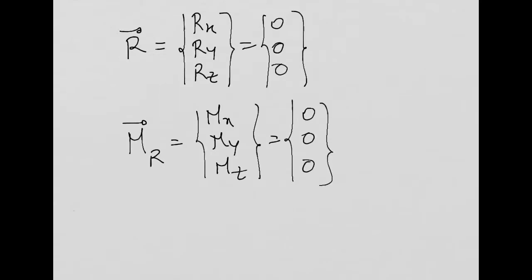Why should the moment be 0? It's the equilibrium equation for the moment. So when we studied the particles, we said summation of forces needs to be equal to 0, the balance of the forces, right? I also gave you an example. You see, we have to do the same for the moments. The moments also need to be balanced. All the moments you have at that point need to be in equilibrium, balance. So that means equal to 0. Okay? So these are the equilibrium equations you have for a statics problem.